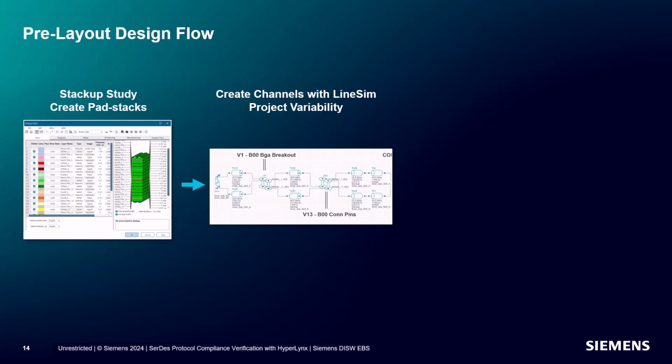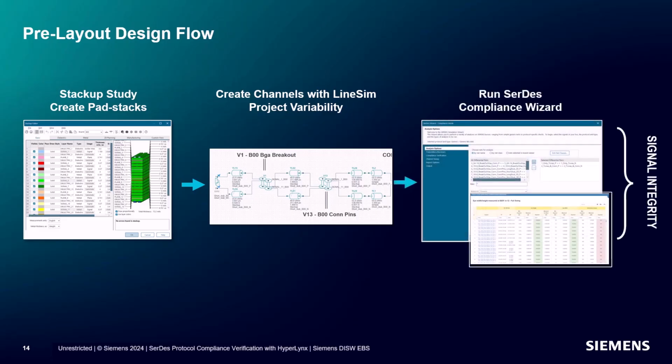We start with 2D via models and get a rough idea if we are passing or not, then create more detailed models as we refine the design. Then, we will run the SerDes compliance check wizard to assess the channel's compliance with the standard and predicted operating margin. The margins we see during pre-layout analysis will be compared to the simulations we performed during the post-layout stage to see if the post-layout results match our pre-layout expectations.